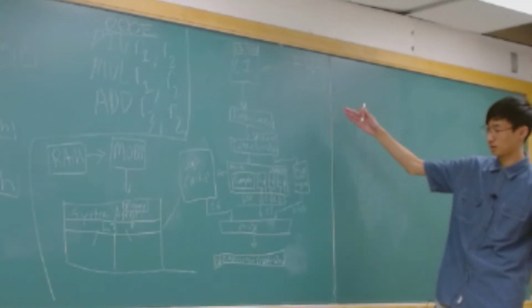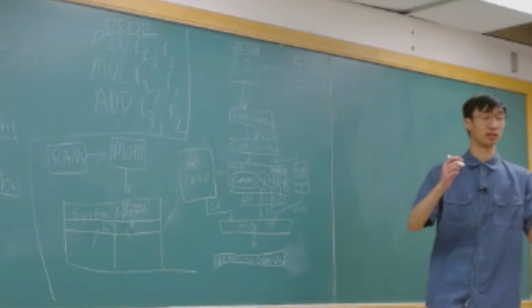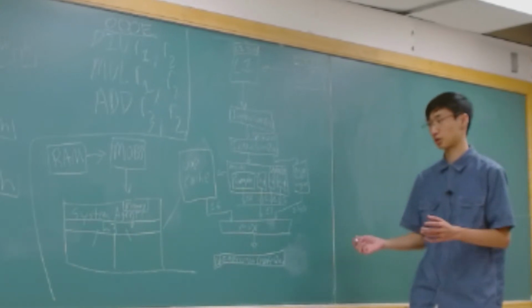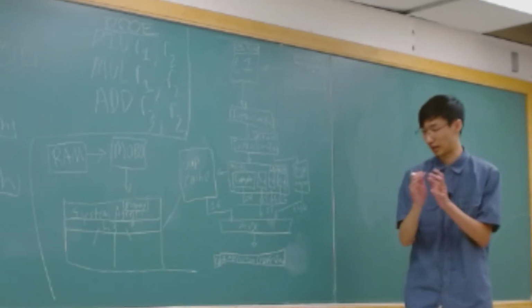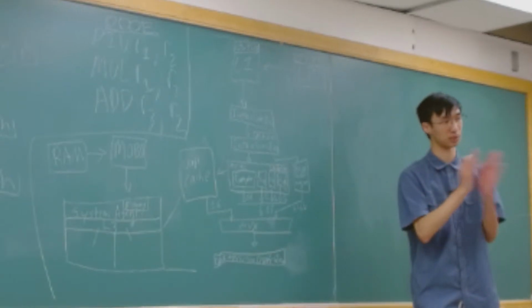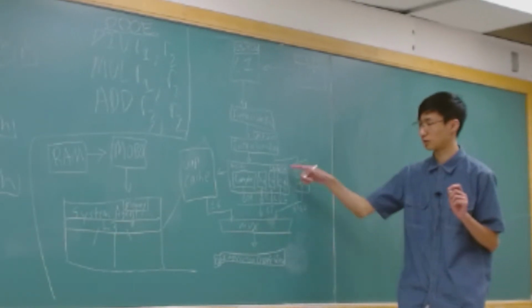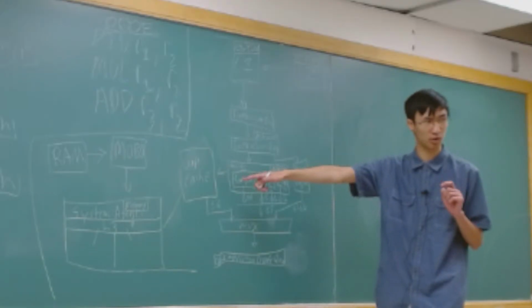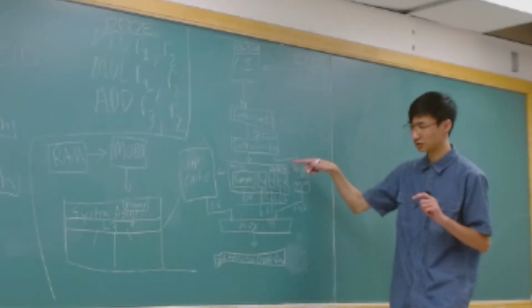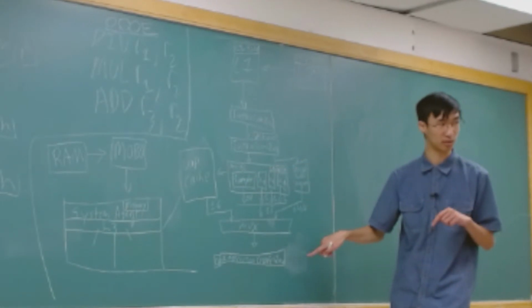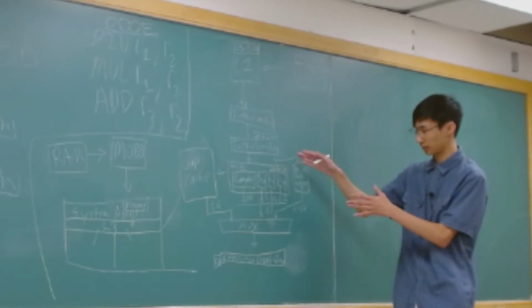But sometimes in some older architectures or some instructions, you can't actually have them together because you're going to need to split them eventually. And if you do microfusion here, then you don't actually wind up putting it in the micro-op cache. So you have to do it here. But I saw a diagram put it here. So we'll put it there.